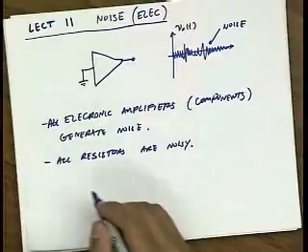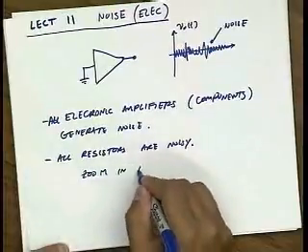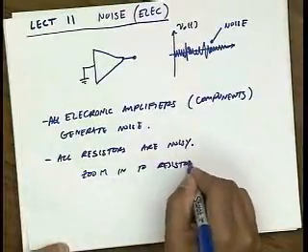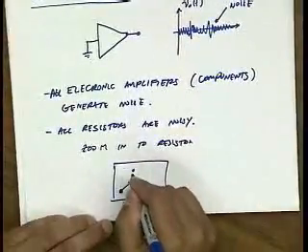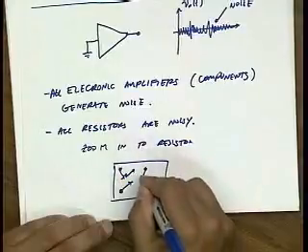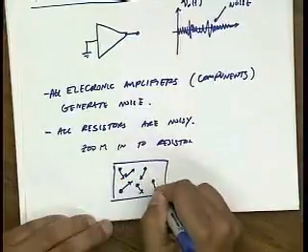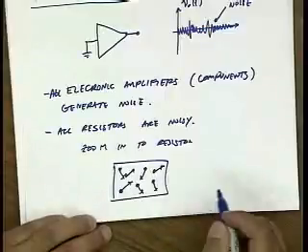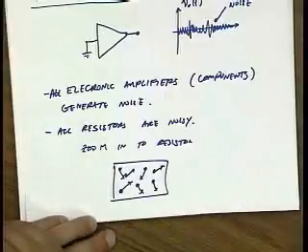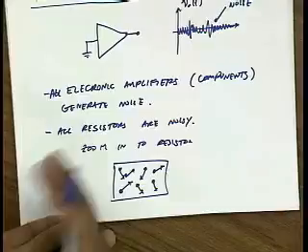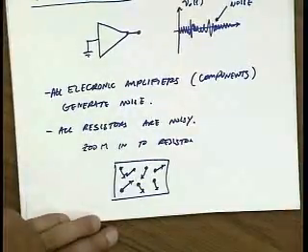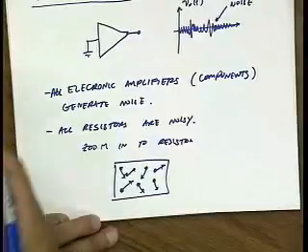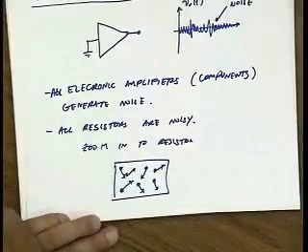If I were to zoom into a resistor and observe the electrons, you'd find them all moving about seemingly randomly and at very high velocities, in random directions. The average velocity is proportional to kT, the average energy. If I take 1/2 mv squared, it's going to be some fraction of kT. So it's a thermodynamic thing.